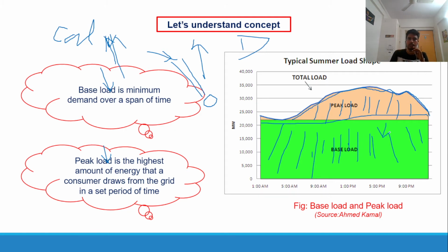Solar can cater to the base load, a bare minimum load, but it cannot take care of all the house loads because it may require more solar cells than the roof area you have for installation. It's also costly in terms of operation, maintenance and the capital investment for installing solar power plants. We find that getting electricity from the grid is much cheaper than installing and maintaining solar. So it's very important to study base load and peak load and to design energy systems that cater to them.